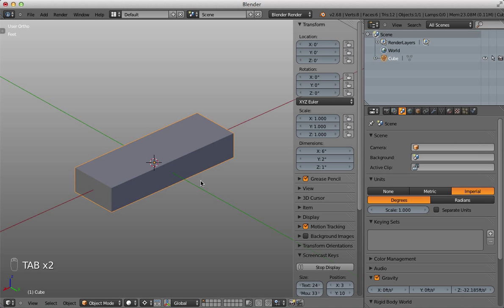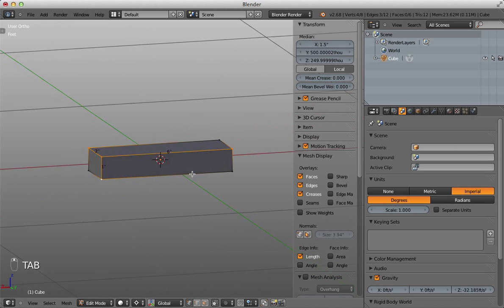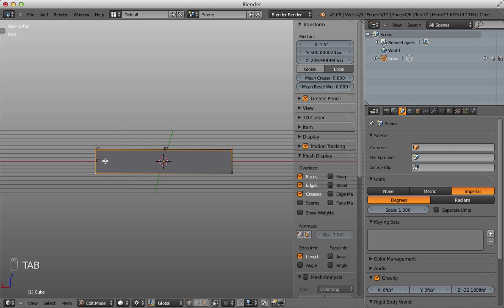Okay. And I also mentioned when you try to model or digitally design a product, think about all the different steps you would do inside the model workshop with foam or wood. And I, for example, in my workflow borrow a lot from those methodologies. So from a side, we know this part is slightly carved out. And with polygon modeling and subdivision surfaces, you can't unfortunately just cut something out.